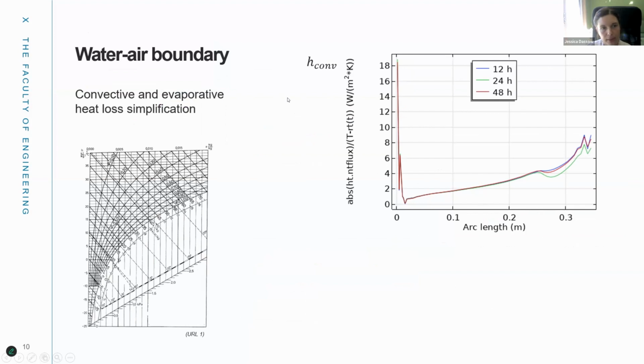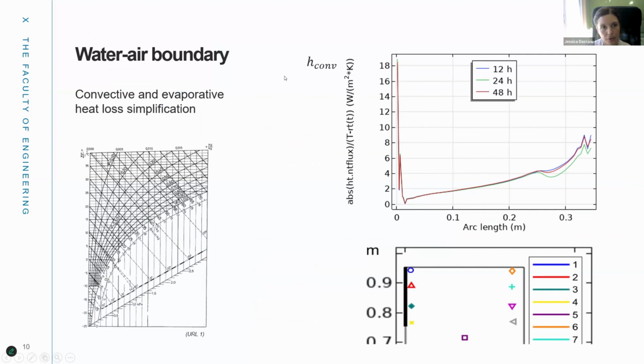So what we assumed was a constant heat transfer coefficient at the surface, so here at our tank. But in reality, if you run a different model where you model the air, you can actually see the heat transfer coefficient isn't very constant. It follows this curve here, which falls down away from the heat source and then rises up again at the walls. So luckily, this is fairly constant in time, so we can use one of these as a sort of function instead of a constant value.